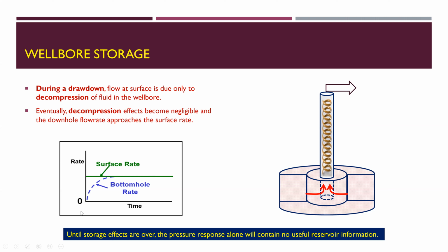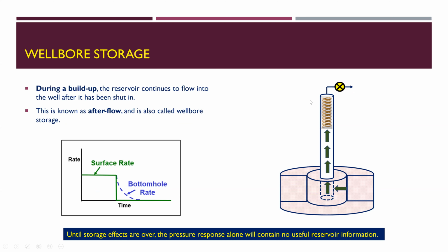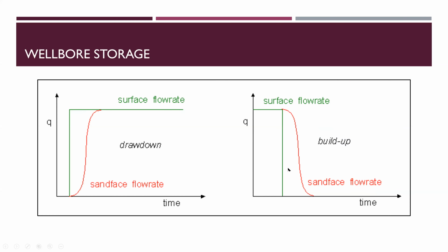However, the bottom hole in reality is not sharp. For the build-up, we shut the well in, however, it's still flowing. The reservoir is still delivering, but of course at a low rate until it vanishes. As much as the fluid is compressible, it will continue flowing. Less compressible, it will not take time. This is a real comparison between the downhole response in terms of drawdown and in terms of build-up.